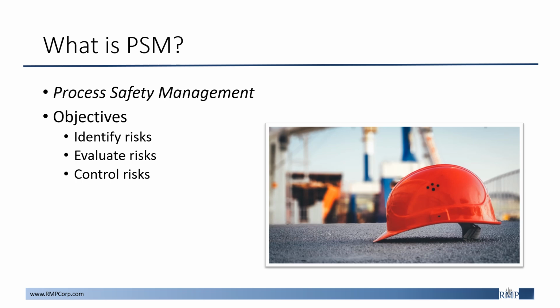PSM stands for Process Safety Management, and the program falls under OSHA, or Occupational Safety and Health Administration. Under the Clean Air Act amendments of 1990, OSHA developed standards for process safety management, which covers facilities that manufacture a list of explosives and other harmful materials. PSM does not apply to the following facilities, which include retail facilities, oil or gas well drilling, or remote servicing operations that are normally unoccupied, and facilities where highly hazardous chemicals maintained on site fall below OSHA's threshold quantity.